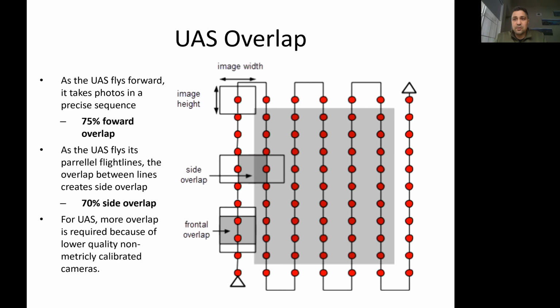Because really, the thing with photogrammetry is, it's a different way of thinking as opposed to traditional photography. With photogrammetry, we really want every photo to appear the same, and I mean the exposure and the shutter and all that kind of stuff. And the really important part of this is having the right amount of overlap, and a consistent amount of overlap throughout the mission. If that stuff breaks down or is inconsistent, you end up with problems in the project, right?